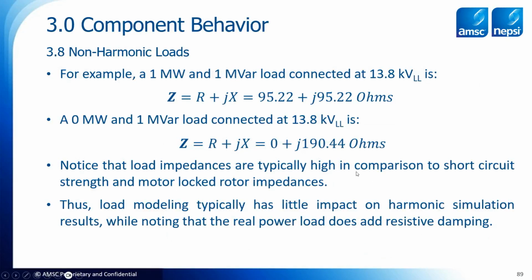What I want you to notice here is that these are pretty high values of ohms, and that load impedances are typically very high in comparison to the effect of the short circuit strength of a motor locked rotor impedance. So when it comes to load modeling, it typically has very little impact on a harmonic simulation, while noting that this additional real power that you put here will affect the damping of the network.